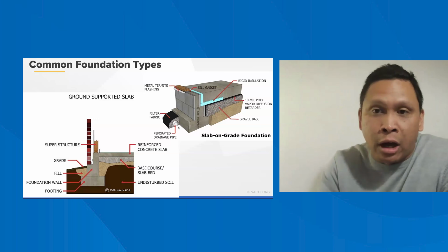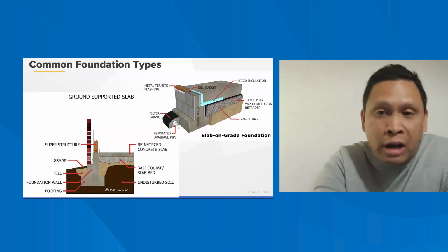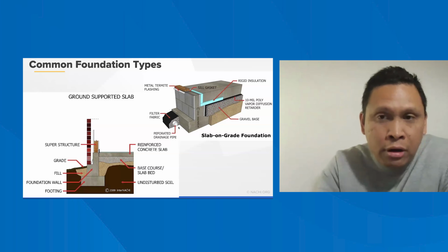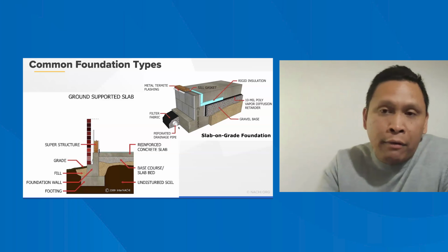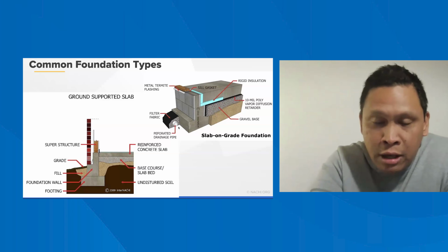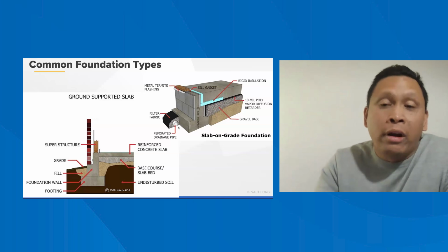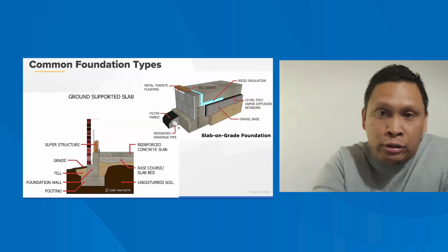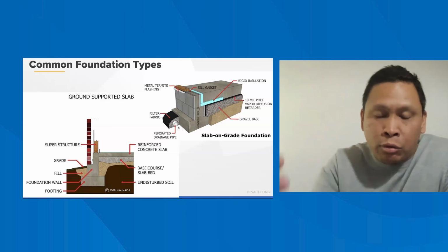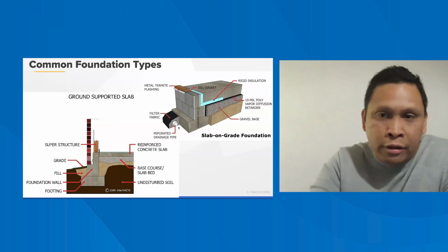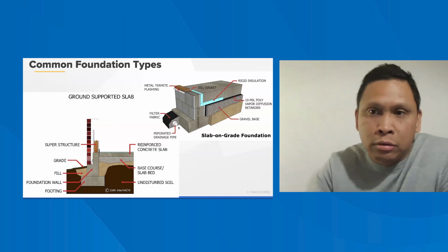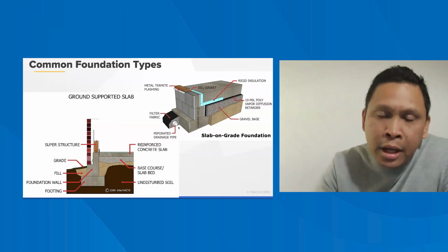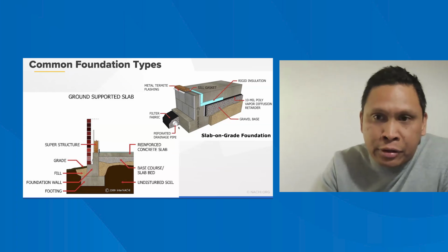So where does that drain tile go? Most of the time it will lead underneath the foundation of the home, and then underneath the concrete floor, and then into what we call a sump pump. Others will call it a crock. That's the actual fancy term. As the water level rises, a motor turns on in the sump pump system and kicks the water away from the home. So that's what that is all about.